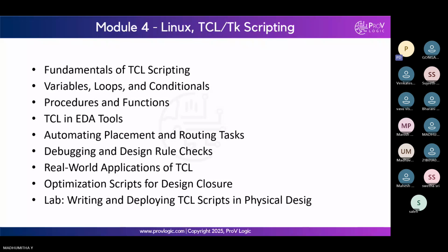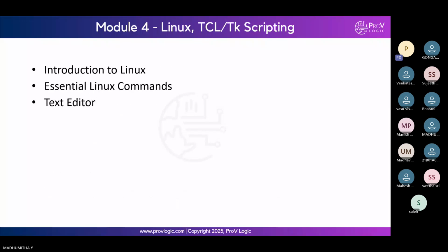And then Tcl in EDA tools. Tcl in EDA tools means how Tcl scripting is used for physical design. Automating placement and routing tasks: how to write a Tcl script to do automatic placement and routing. To do a design rule check, how to write a Tcl script. Like this, we will see some real-time applications, and lab access will also be provided for this module.